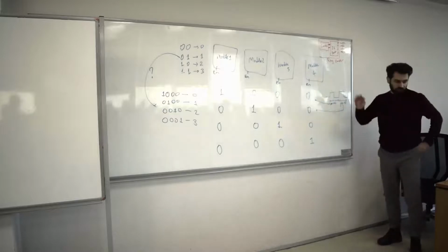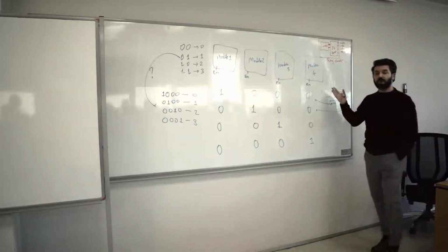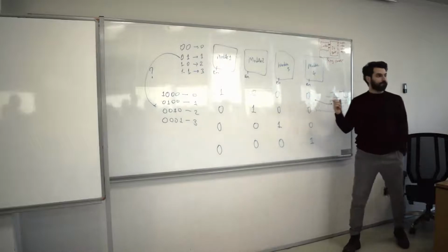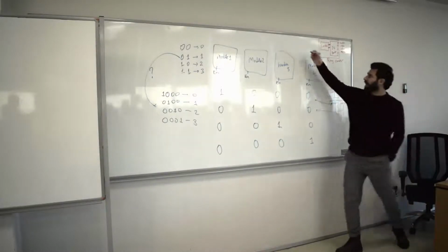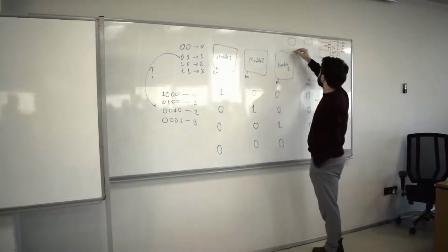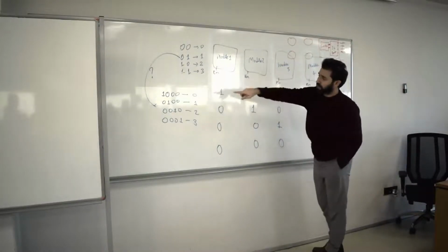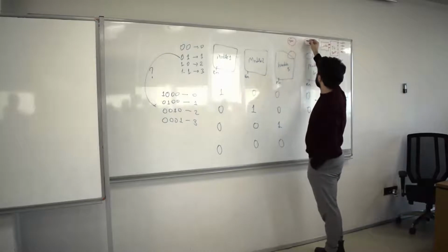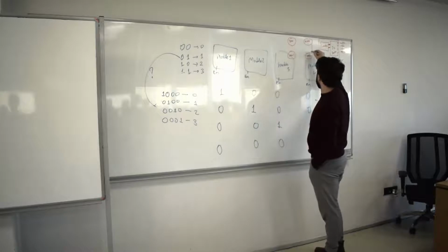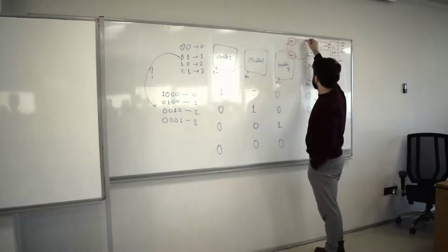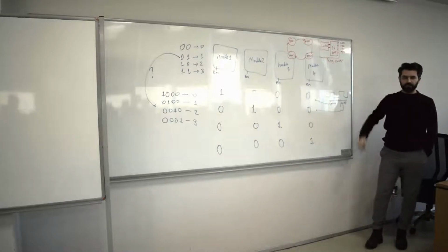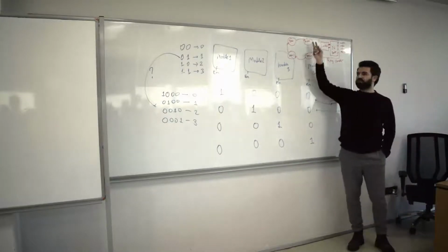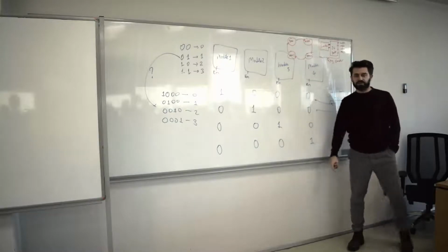Okay, so this is good. However, there are a couple of problems with this ring counter. First of all, you can also draw, by the way, the finite state machine representation of this counter as having 4 states, right? And each state is represented by those 4 bits: 1000, 0100, 0010, and 0001. And that is your finite state machine representation or state diagram of this counter. We just used 4 bits instead of 2 bits to represent those states.